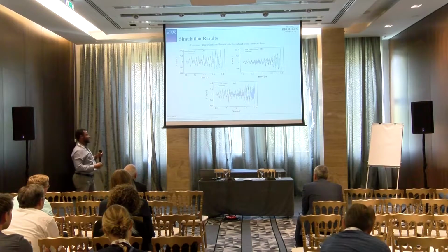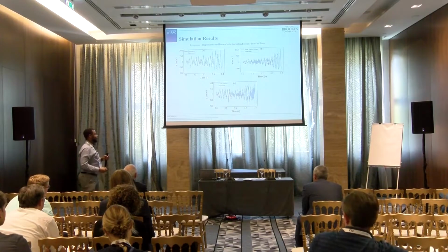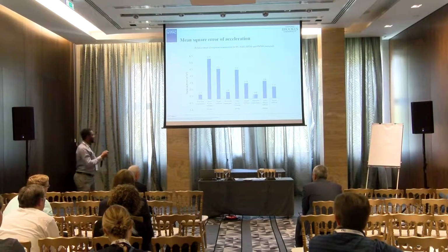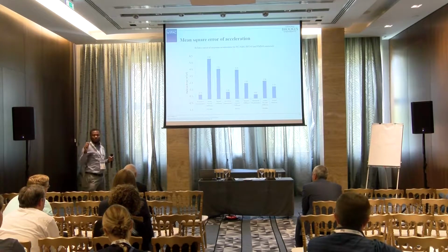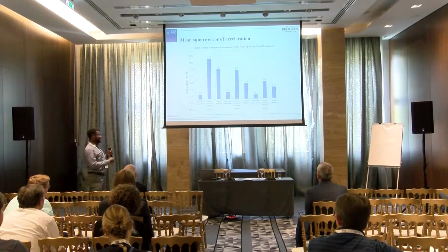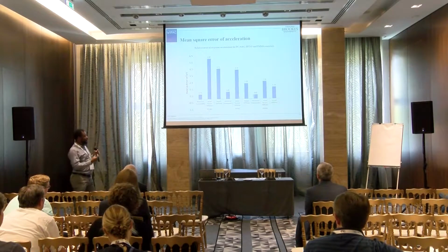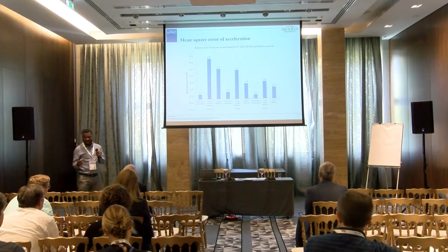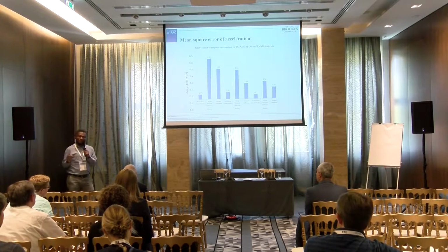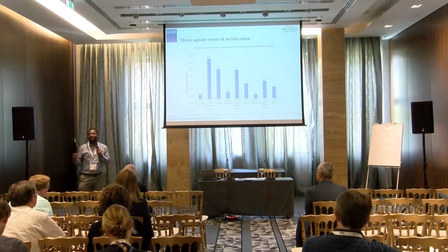And we established the error. We have a relative error, and you can see that the nonlinear hyperelastic has a very small error compared to the others, which have very huge error. So that tells us that using a linear model of either secant or tensile modulus to model our dynamic response for nonlinear materials such as polymers would give us quite large error.